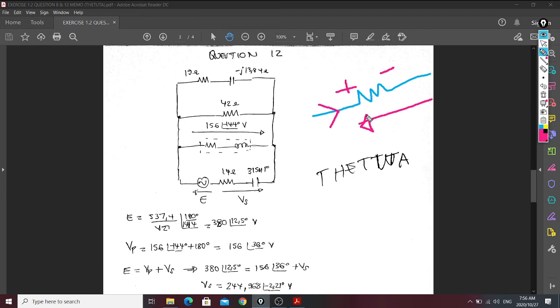The idea is that every time they give us a voltage in the circuit, where they give us the arrow, we need to check if this arrow is going in the right direction. Can you see? So we come here: this arrow from the supply, with positive and negative, tells us the current is going in this direction. When you come with this current, it splits in three. You have I1, you have I2, and as well I3.